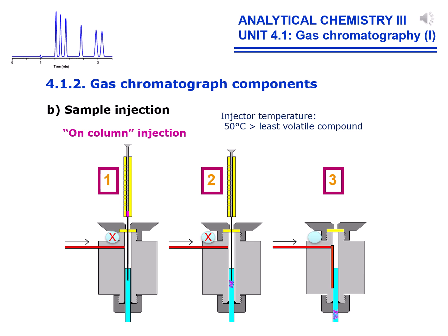With the aid of the microsyringe, a sample amount is injected through a silicone septum directly into the injector port where the column head is located. The injector temperature provided by the metal injector block must be sufficiently high for the sample to volatilize completely without decomposition. This is called flash vaporization.